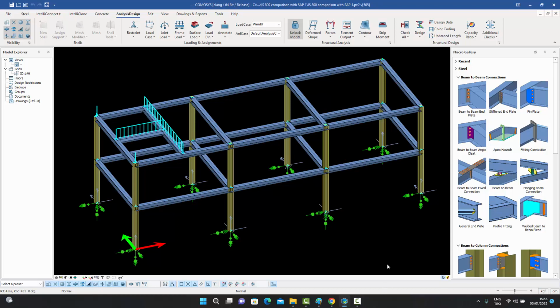As you know, you can select all of them and you can check what their existing states are. So let me select this element over here and go to the check selected option over here. Like I said, you can select all of them, or you can select any one, just say check all. But let me just go and check the selected one. And when I do that, immediately it does the design check of that beam, for example, according to the Indian standard.